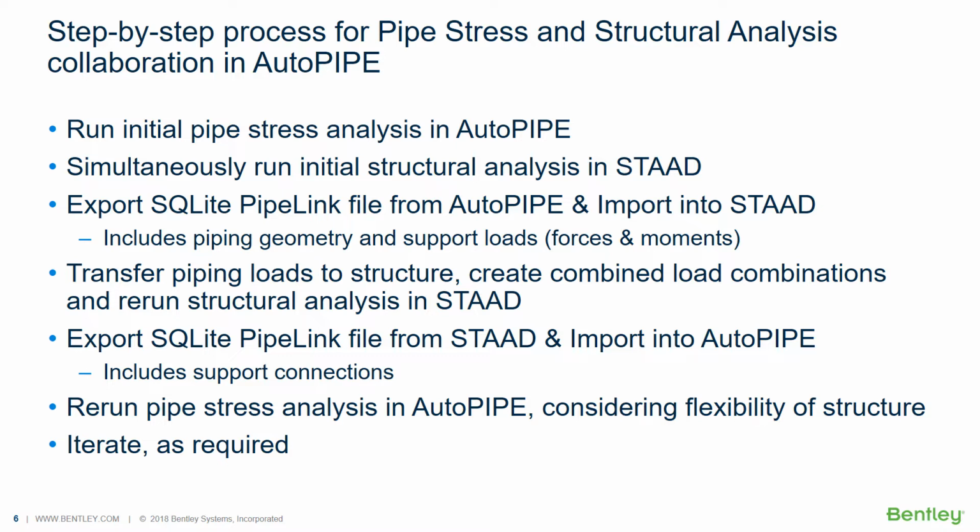At this point, a lot of engineering companies and a lot of engineers stop and say, okay, my piping analysis is good and his structural analysis is good, so we're good. On the structural side, a lot of companies go a little bit further and take into account the piping loads, but they do that through hand marked up isometrics or printed out support load reports. A lot of that has to be a manual entry on the structural side. So a lot of times the structural engineer takes this a step further and actually includes the piping loads in their structural analysis, which is great.